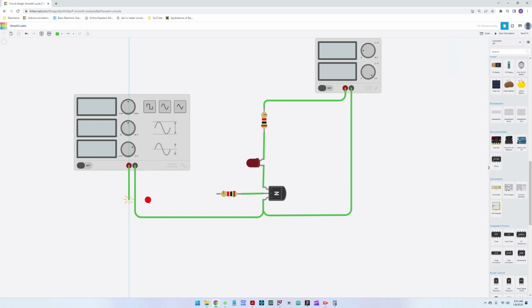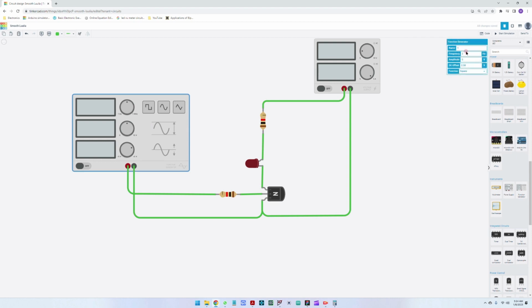Okay, let us then connect the positive line from the signal generator and check again, frequency 2. The supply we have to increase a bit, just so that we have a bit more voltage driving here. And for the resistor, let's put a smaller value here, let's say about 400 ohms. Yeah, it would be enough. And here it's 1 kilo, it's more than enough. Okay, let's start the simulation and see if this LED turns on and off.